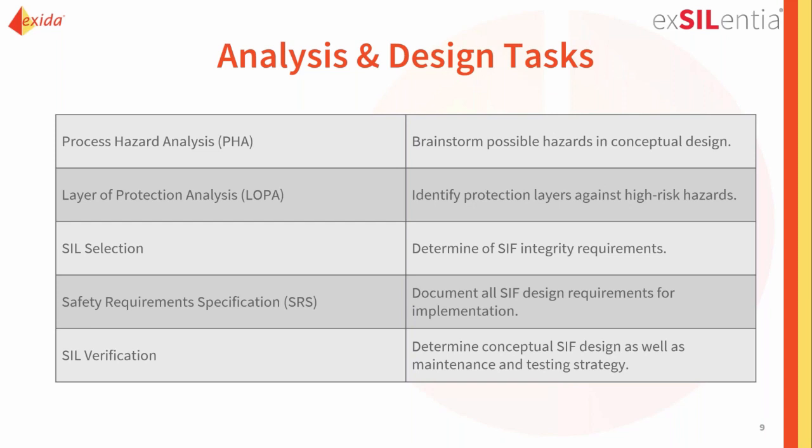on. Then obviously after that, when we operate the plant, we need to record proof tests, we need to record failures and so on, and we're not really covering that here in this webinar. Obviously within the exSILentia software, there's a strong component, SILstat, that addresses that, but we're focusing on proof testing, or basically defining the proof testing strategy.